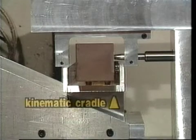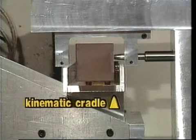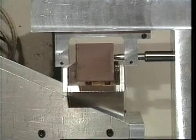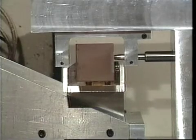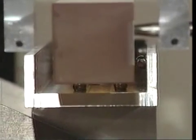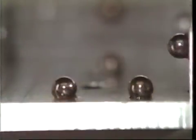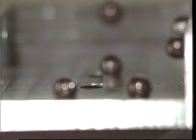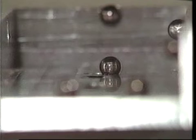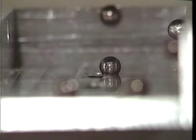The straight edge will be held in a kinematic cradle. The straight edge should be level and its center line should be located at the height of the spindle and tool center lines. The design of the kinematic cradle allows the straight edge to be supported by the minimal 6 forces, thereby avoiding overconstraint and the resultant variable deflections and positioning uncertainty. In this manner, the kinematic cradle helps to ensure that the reference surface is uniformly positioned for both steps.